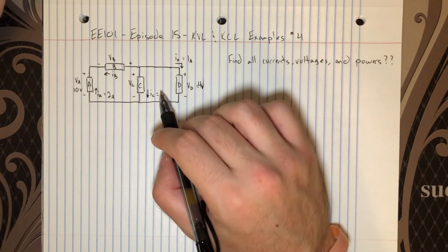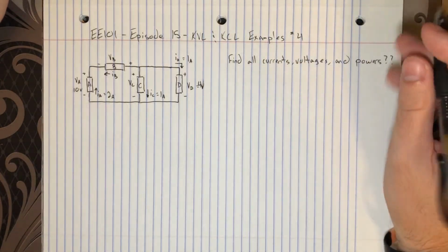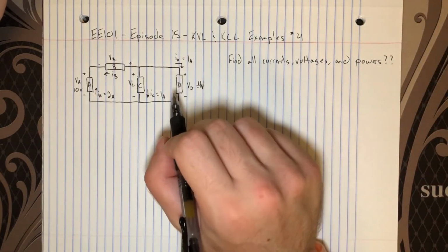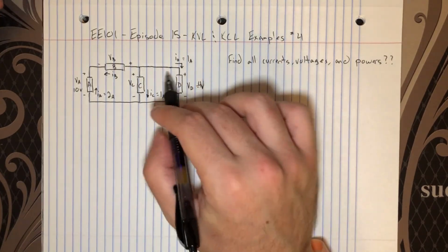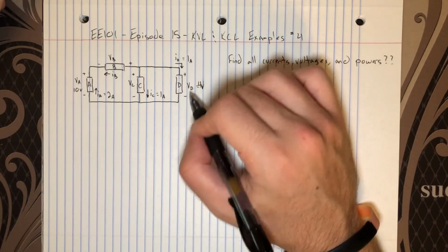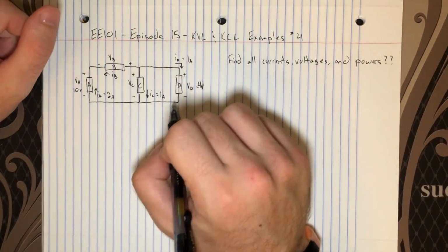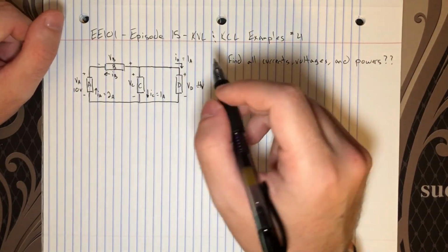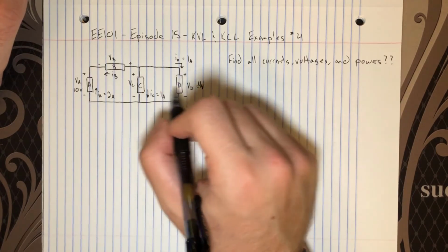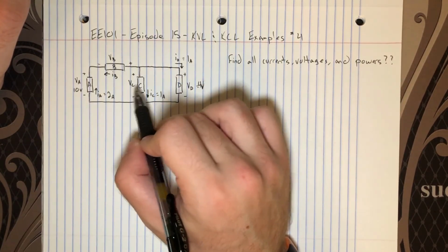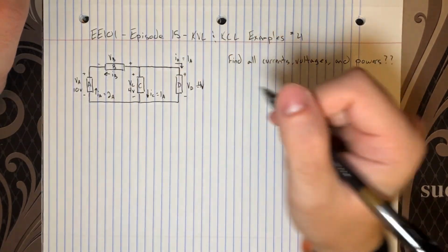And this is actually the trivial case of a parallel circuit, so we don't even have to write out any algebra. This should be very clear. These 2 elements are in parallel, and they share the same polarity here, and they must because they're in parallel. Even if I had drawn the polarities the other way, you would then recognize that one of them is incorrect, because they must have the exact same voltage since they're in parallel. Given that we know VD is 4 volts with this polarity, VC therefore must be 4 volts with the same polarity. So the initial polarity markings are correct, and we know that VC is 4 volts. And that's fantastic.